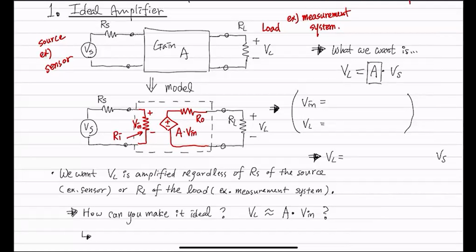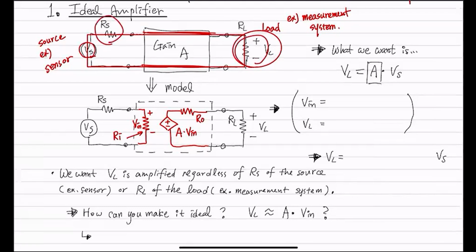You may think, I'll just connect it from here directly to there so that we measure something, right? But let's assume you actually connect it like this: your source through a resistor and another resistor, and it comes back. Then the value you measure here is divided into two pieces. So if you really connect it like this, your measurement is always going to be smaller because it's divided across two resistors. That's the reason why it's not connected like that.